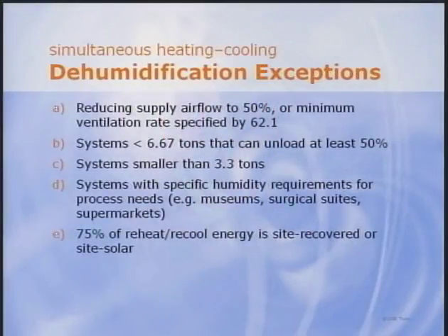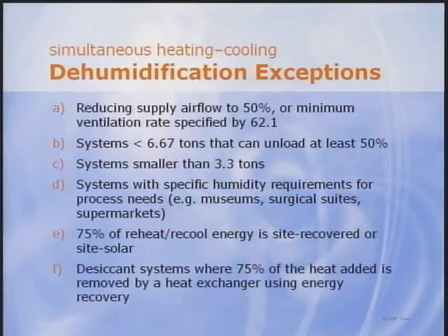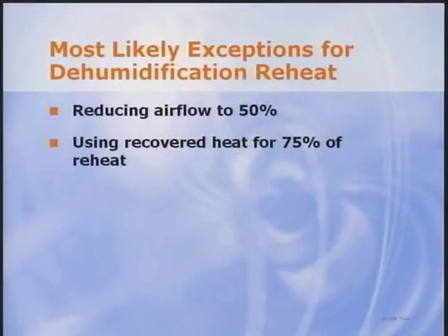The final exception is targeted toward active desiccant systems that dry but also heat the airstream. Often these systems require recooling of that hot, dry airstream. As long as 75% of the heat added by the desiccant is removed by a heat exchanger using energy recovery, the system is allowed. As Dennis showed, most VAV systems don't need humidistatic controls.